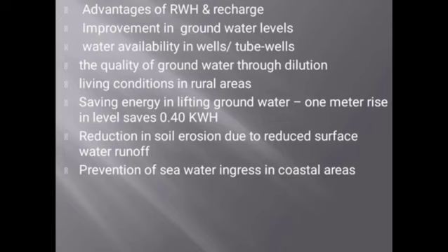What are the advantages of rainwater harvesting and recharge? Improvement in the groundwater table, water availability in wells and tube wells, the quality of groundwater through dilution, living conditions in rural areas, and saving energy in lifting groundwater. A 1 meter rise in level saves 0.40 kilowatt hour. Reduction in soil erosion due to reduced surface water runoff. Prevention of seawater ingress in coastal areas.